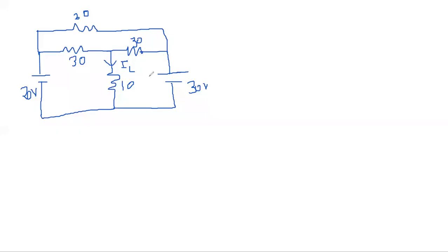First you see in this diagram that there are two voltage sources. So this can be easily done using the superposition theorem. Then you have three loops. You can easily do it with Kirchhoff's voltage law, but it is very difficult to apply Kirchhoff's current law here.